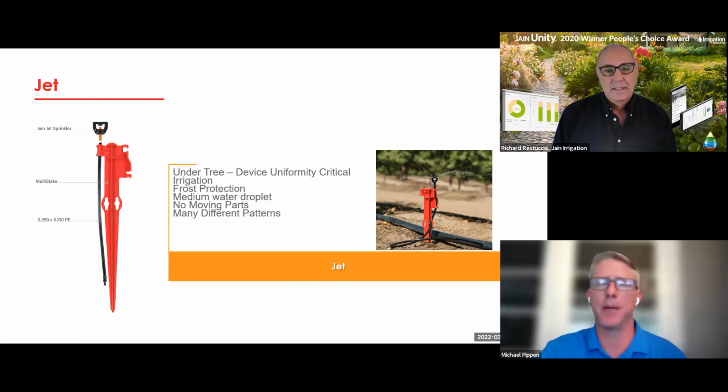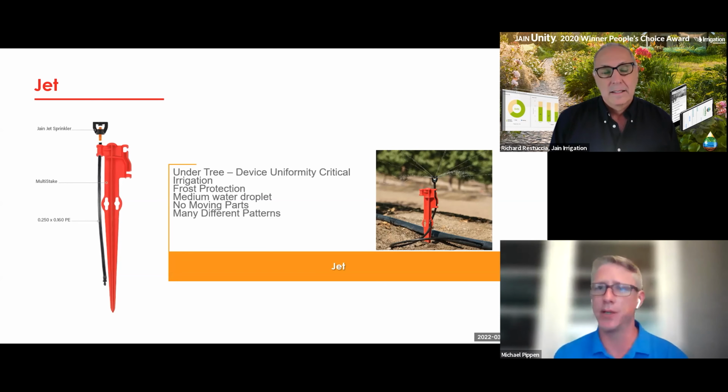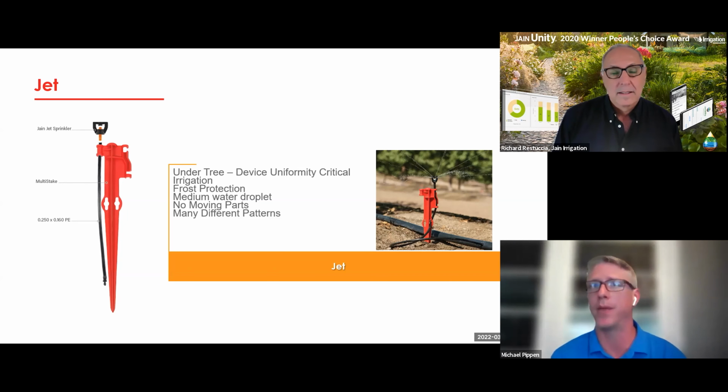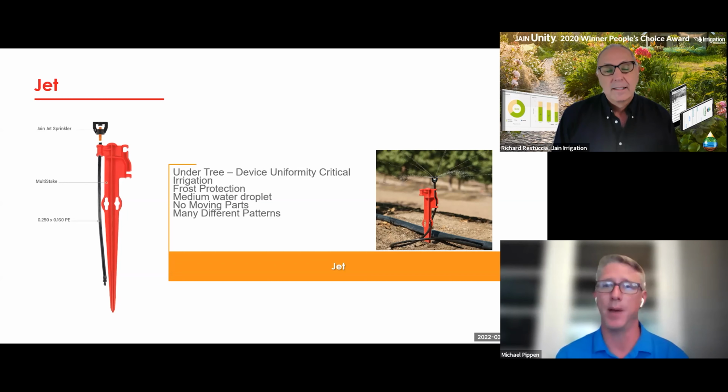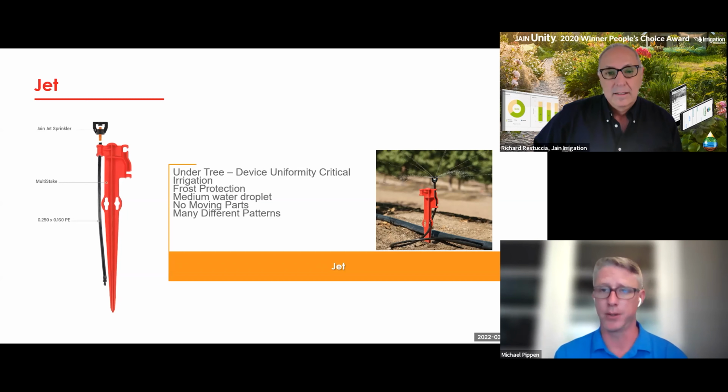No, they would not typically be a head-to-head throw. We again would be looking at these jets and micro sprinklers more about individual devices per tree, usually a single device per tree. But you can get some spacings where, typically I think of pecans in the Southeast having a pretty wide spacing, maybe as much as 40, 45, 50 feet. In that case, one little micro sprinkler is just not enough to cover the root zone area. So we'd actually have 2 per tree.